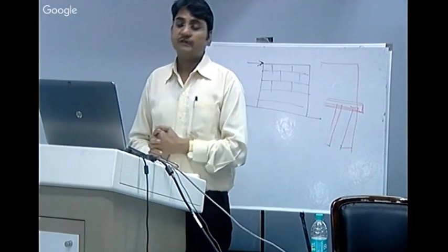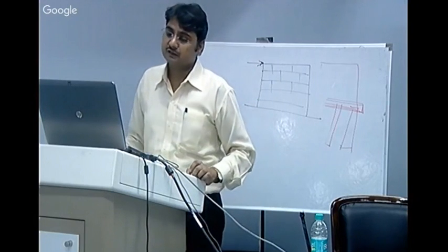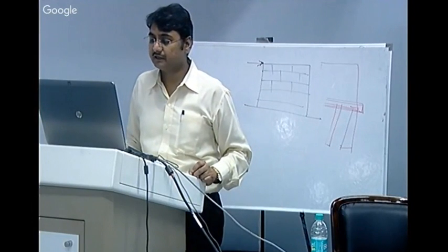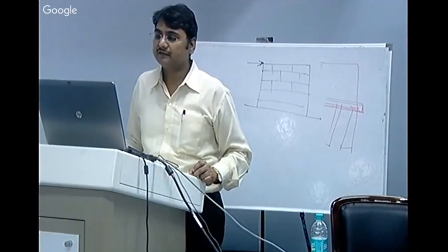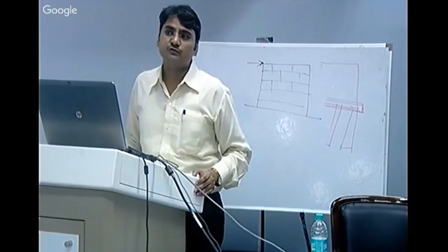So in the concluding remarks, if your building has a light roof structure connected together, horizontal and vertical reinforcement, regular and symmetrical buttresses, a flat, firm and dry site, and good quality of construction, then your house will be happy.